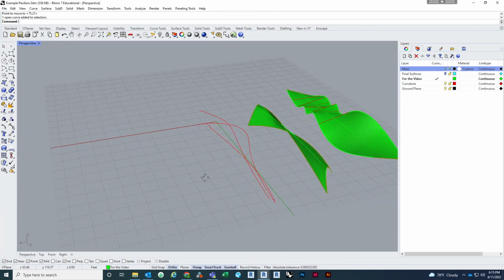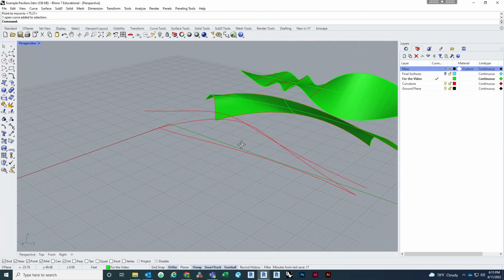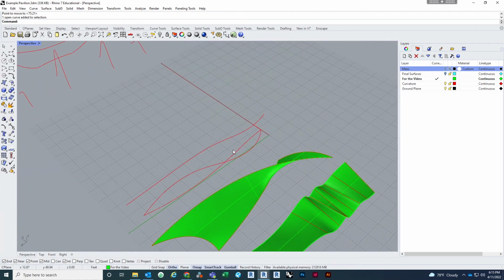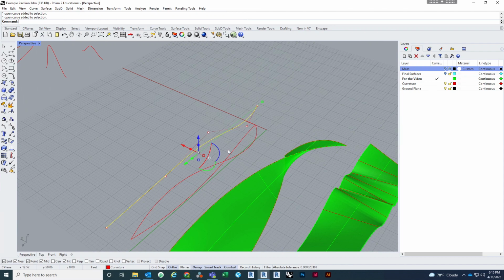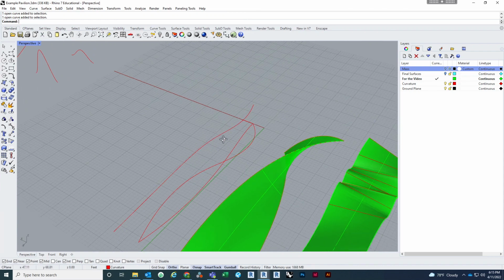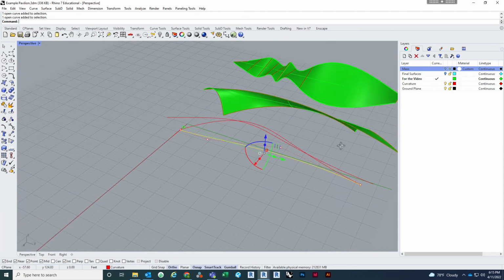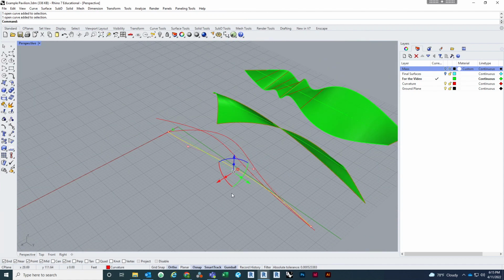And one thing I think is really important, just from a fundamental modeling standpoint, is you want to make sure that each curve has the same amount of control points. And the way to make sure of that is to rebuild the curves. Now the easiest way actually is to just create the first curve, copy it, manipulate it, copy it, manipulate it. That way you'll have the same curves. But if you wanted to create all 3 separate curves with different control points, you'll select the curve and then type in rebuild,